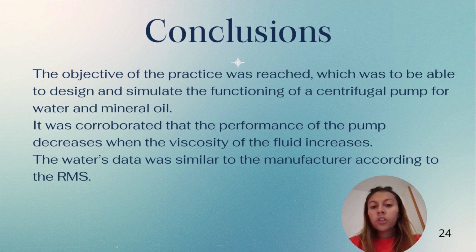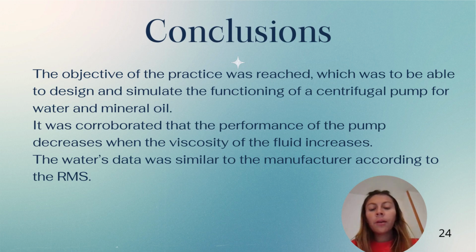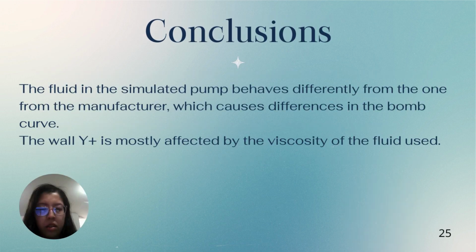Well, as a conclusion, the objective of the practice was reached, which was to be able to design and simulate the function of a centrifugal pump for water and mineral oil. It was corroborated that the performance of the pump decreases when the viscosity of the fluid increases. And finally, the water data was similar to the manufacturer's according to the RMS. Also, the fluid in the simulated pump behaves differently from the one from the manufacturer, which causes differences in the pump curve. Finally, the head loss is mostly affected by the viscosity of the fluid used.